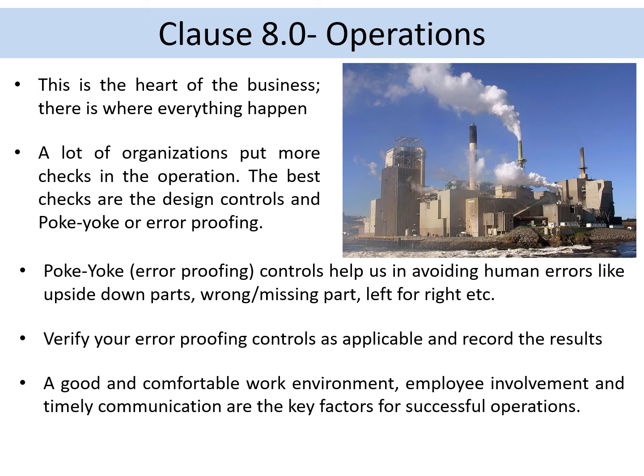The best checks are the design controls and poka-yoke, or error proofing. So if you have error proofing or poka-yoke in your process, please make sure that you check those poka-yoke if they're functional every start of every shift. That is very critical. And record your results in the form given to you by your supervisor.